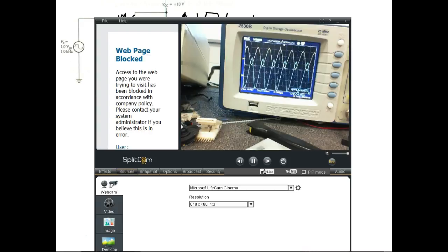So what happened to the gain? Well, the gain went from 70 something down to 1 point something, about 2. So if you're in an amplifier and you're getting nowhere near the gain that you expected, then that would be one of the problems you anticipate. Okay, guys, y'all go ahead and take a break.